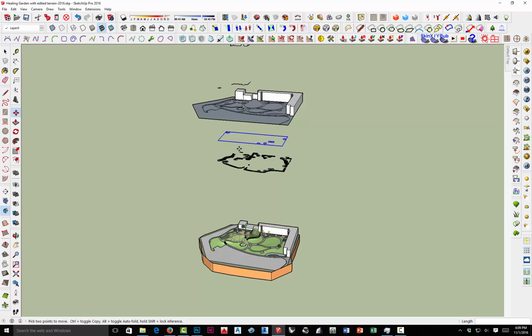If you haven't used that preserve drawing origin from the very beginning, AutoCAD files will come in different places. But you can use a known object in order to move them and align them, and that way when they drop, they're going to end up in exactly the correct position. So use that technique if that's a problem. It's really pretty easy. You may have to re-W block a few files for the plants, but that's okay. It'll allow you to bring each one over, line it up. Just make sure before you do that that you group all those things so that it's easy to separate from any of the other geometry that you're already snapping to.